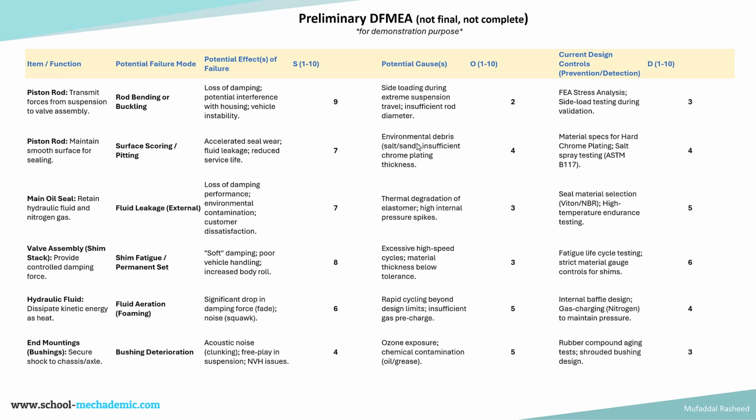The potential causes can be that some debris has come into contact with the rod, and the debris has caused scoring or pitting on the rod surface. Or it can be that there is insufficient chrome plating thickness. So the chrome plating on the rod, which makes sure that the surface finish is optimal, is not sufficient. That can also be a potential cause of failure.